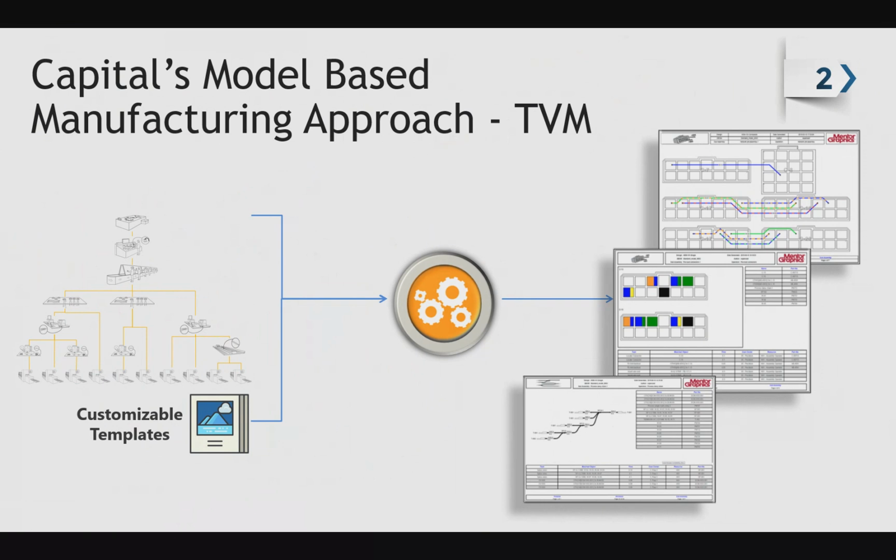Essentially, each of the operations is tagged with a workbook template, which is highly configurable through the use of providers or Java apps that pull the harness information into its map destination on the template. These provide rich controlled output formats that conform to quality standards, minimize training needs, and reduce the likelihood of misinterpretation by production staff. Since they are generated automatically, they eliminate errors and minimize costs of manufacturing documentation creation.